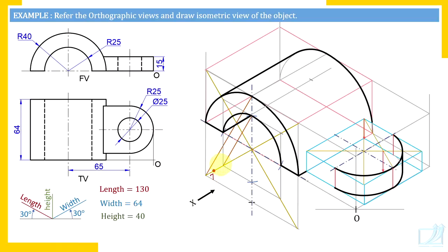7 millimeters we have moved that center. And take the radius of this bigger arc in compass and draw an arc here. Now we just want to create this joint here. We know that this joint is not a straight vertical line. It is a joint on a curved surface. So draw a small arc here. You need not draw an unnecessarily very long arc. Just draw a small arc here.